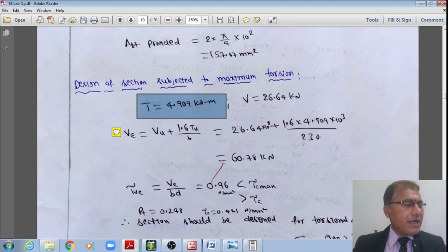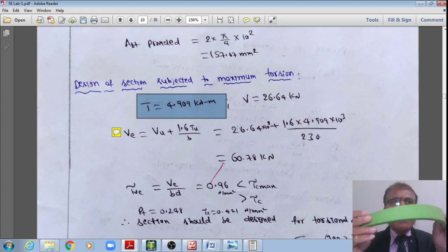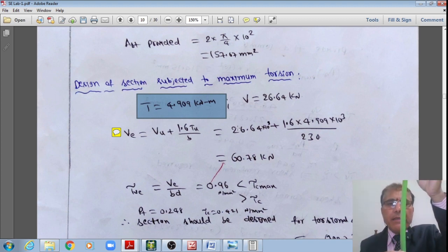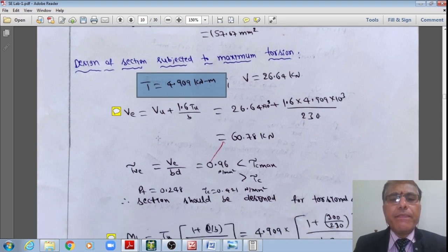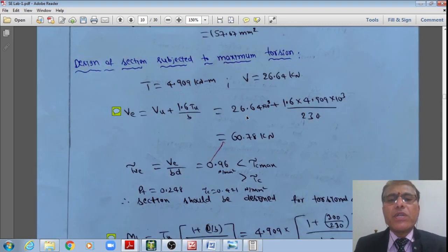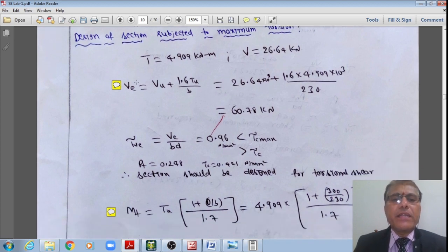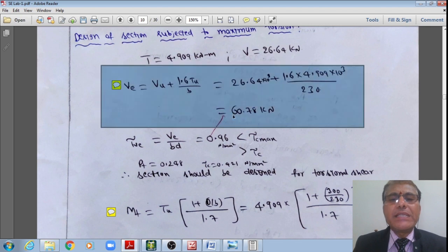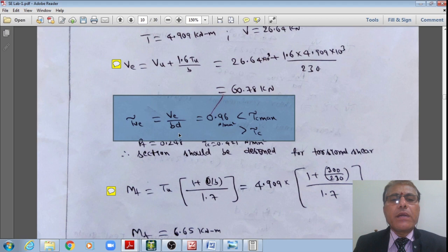That indicates the effect of torsion in curved beams or ring girders in water tanks, or in the ring girder beams of deep bins. Therefore, we cannot neglect the torsion. Almost 128% increase cannot be neglected. This formula will take care of that increase in shear stress. With this shear, now I'll calculate the equivalent shear stress.